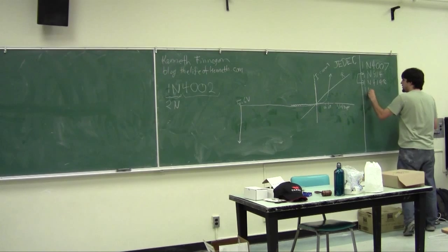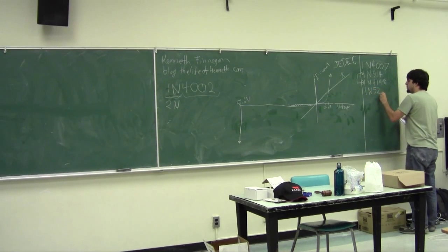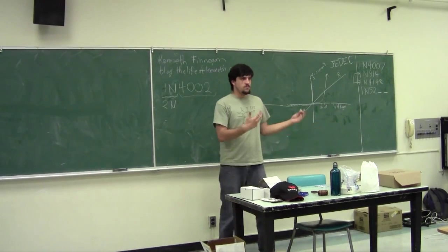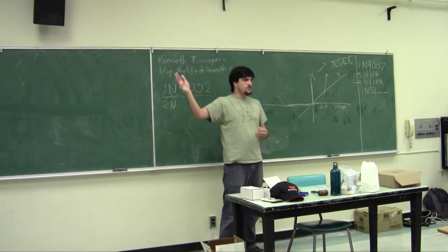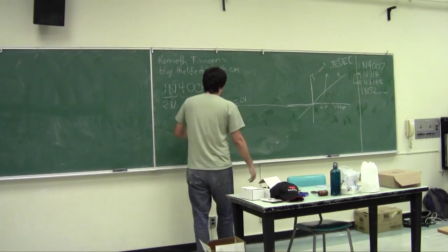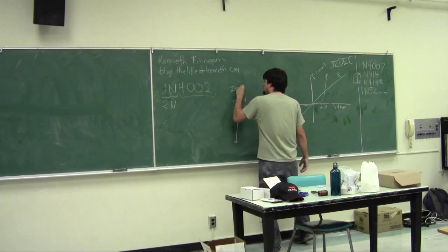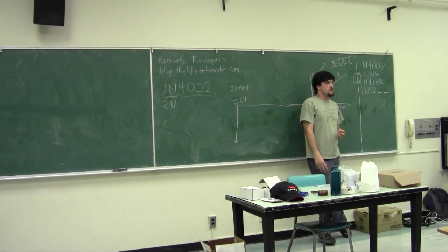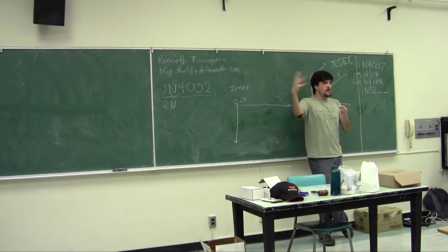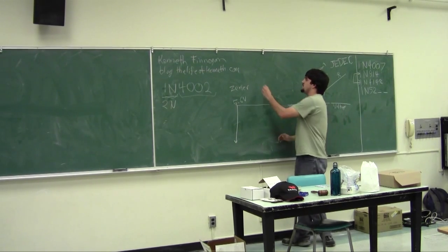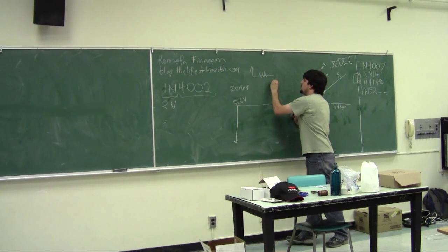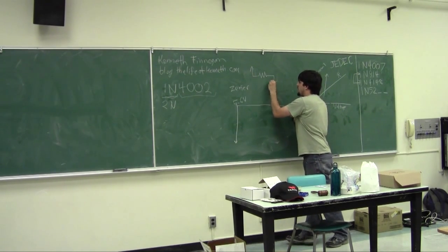So there is a whole series that starts with a 5 and then a 2 and then 2 more numbers that give you every single voltage from 1 volt up to several dozen volts. This is called a Zener diode. Zener diodes are very useful as a voltage reference. If you want to build a voltage regulator, you need some reference to then regulate against. I'll show this later, but essentially, if you have just some high voltage and then a Zener diode,